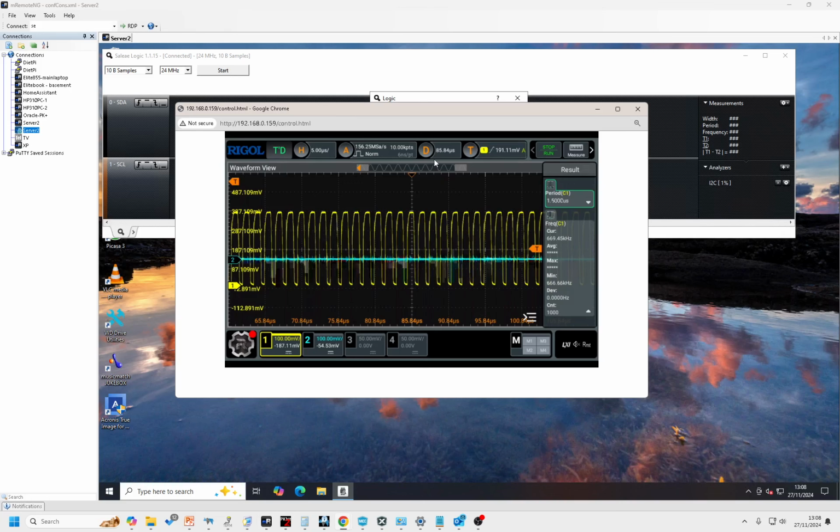I've got an oscilloscope running here, and I'm going to show you what happens on the scopes to start with, then we'll look at the source code, the .s source file. I am waiting for the clock signal to drop. It is currently passing the compilation to PIC-AS. It is currently programming it with a PIC-Kit 4.